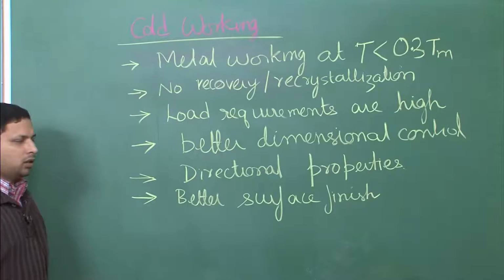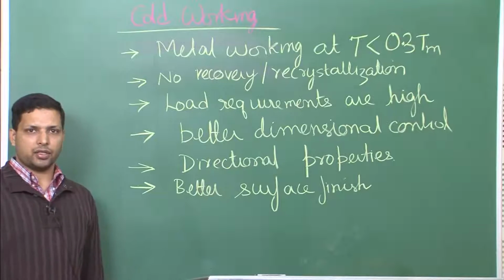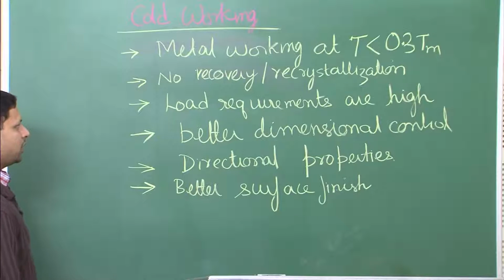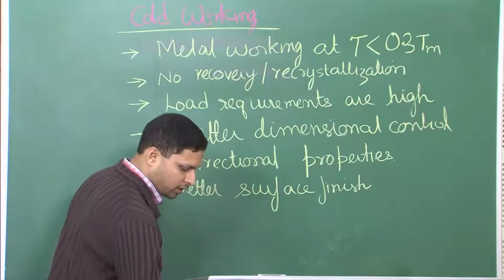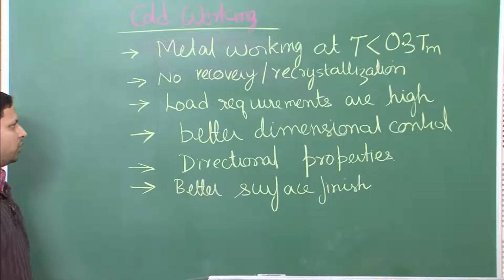So, most of what we have discussed here for cold work are its advantages. Now, let us also look at some of the negative points or the disadvantages when we are deforming a material by cold work, and one of them I have already listed out, and that is high load requirement. So, what is the drawback of high load requirement? It would imply that you will need equipment with much higher loads.